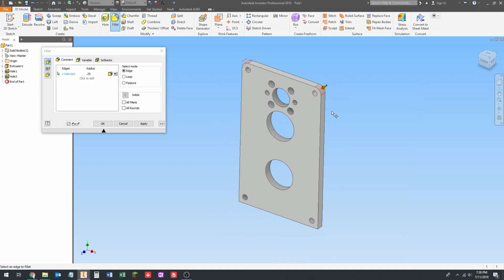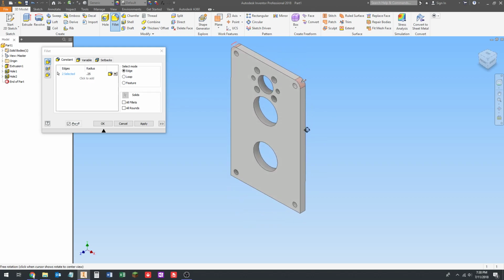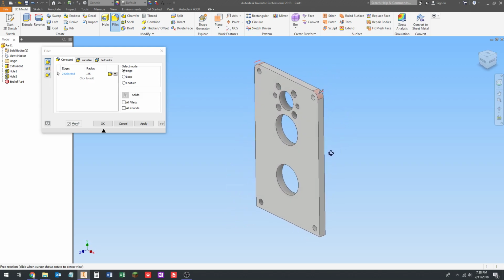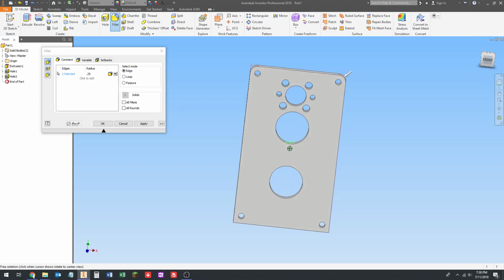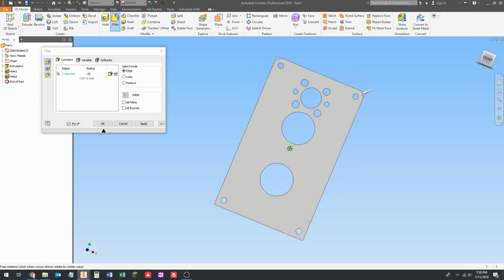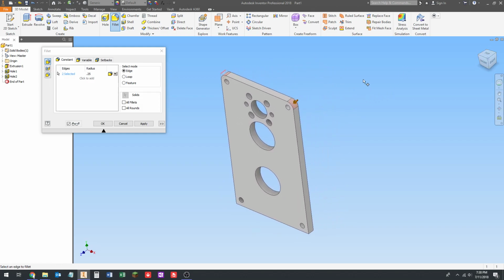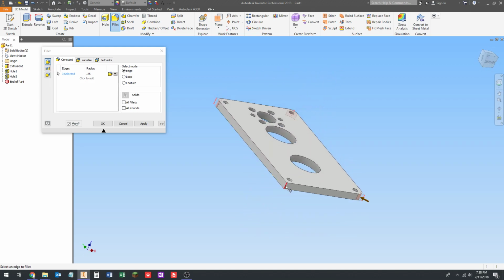So I'm going to click all 4 of the edges. You're going to have to use the orbit tool, or the orbit feature to do this. If you don't remember how to do that, you hold the shift key, you press down the mouse wheel, which is the middle mouse button, and then you move your mouse around to orbit. You can also left click and hold and drag on this little view cube up here in the corner. The view cube tends to snap to different views, like the front view and stuff, so it's sticky and it drives me nuts when I'm using it, so I never use it, but a lot of people do. So alright, anyways, finish selecting these corners.